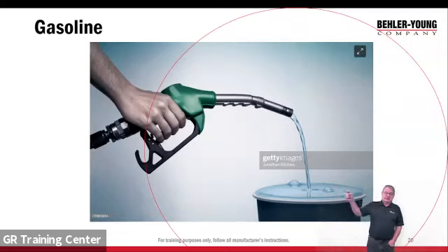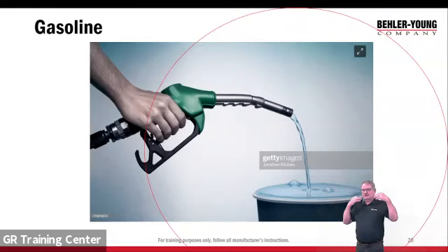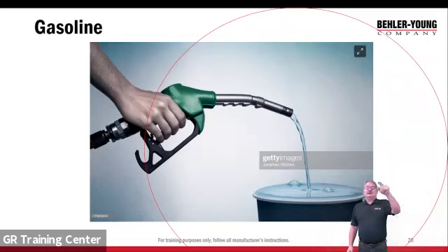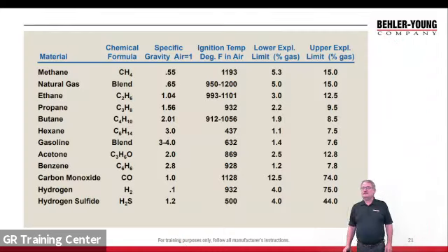Now, if I move down to the liquid, if I could actually get a match into that liquid without the vapor being there, it's not going to light, because it's above its explosive limit, its upper limit. It's liquid. I don't have any oxygen, so it won't ignite. It's not until I vaporize, like in the circle here, where I'm in that limit. I'm above my minimum, but I'm below my maximum, that it will ignite, because I have both the right amount of oxygen and the right amount of fuel, and any source of ignition is going to light it off.